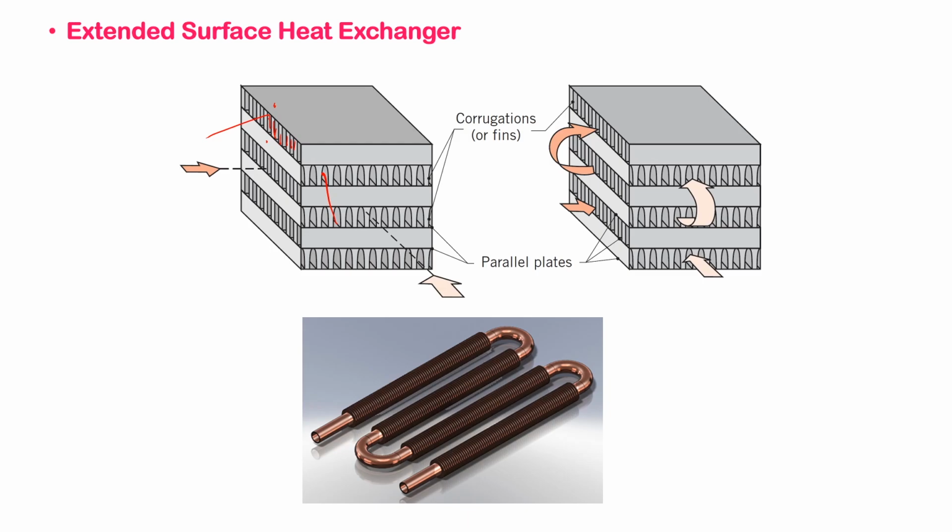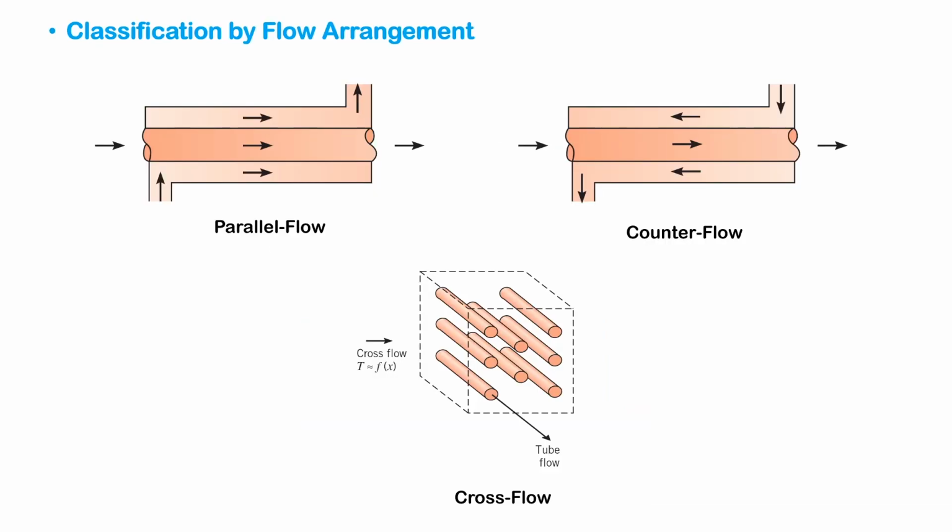Another type is a tube that has an extended surface. Let's say there is oil here, and there is a hot gas here. We have cold oil, and we want to heat this up. That could be one possibility. You can flow the gas around these extended surfaces. So now let's further talk about different types of direct transfer heat exchangers.